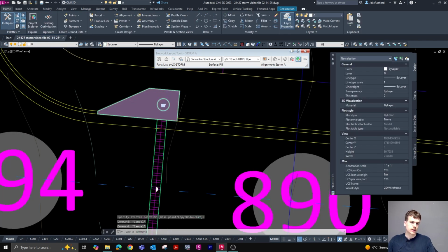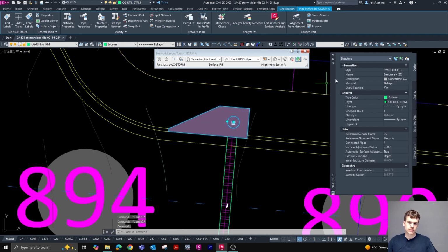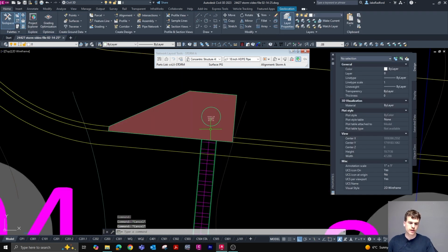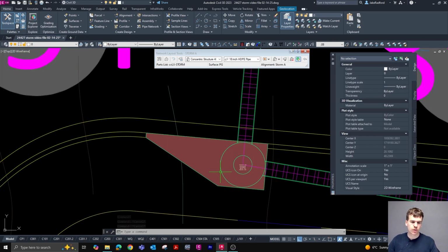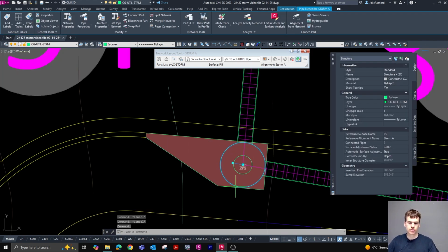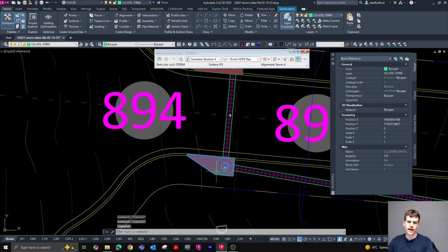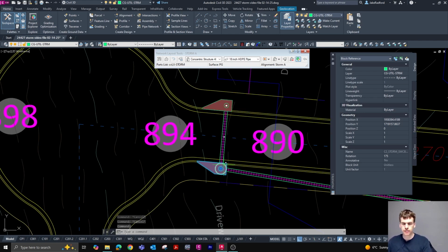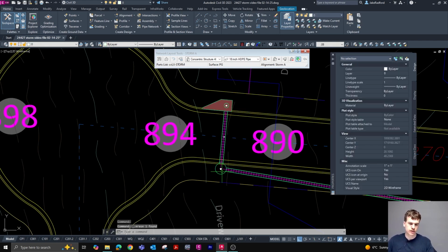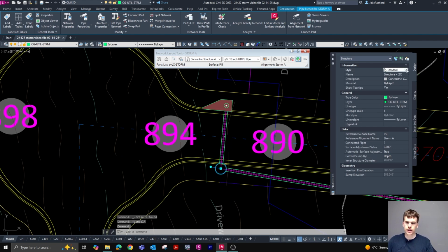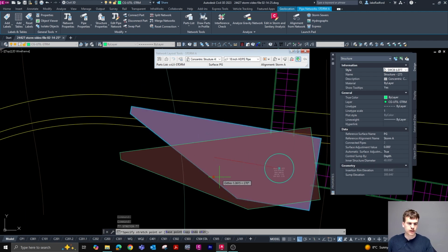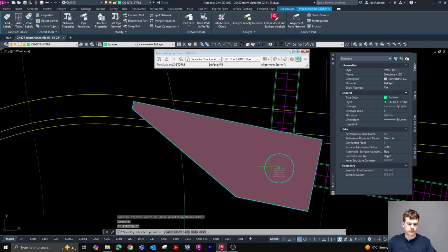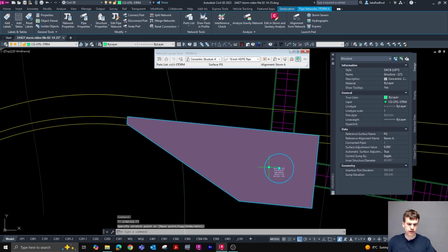As so. And now when we click on the single wing catch basin, we're selecting our structure. So our structure is appearing as a single wing catch basin, which is exactly what we want. So we don't want this double, just a circle as a structure and then the block itself. We want to be able to just grab the single wing catch basin and it be the structure itself. So we're just going to delete this block, and then this guy is going to be a single wing catch basin left. And so we can do this for virtually every different structure type because we have styles for virtually every different structure type.